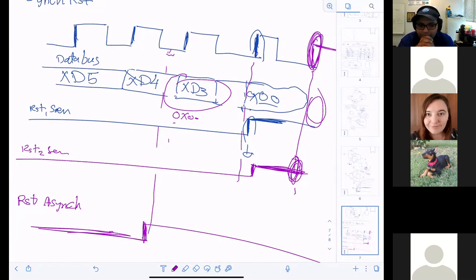It resets when the clock is high? No, not clock high. It's basically on the edge with the reset high. When it's asynchronous, what will happen? It'll reset anytime you press it. When the reset is active, I'm done. Make sense? It doesn't have any relation with the clock.